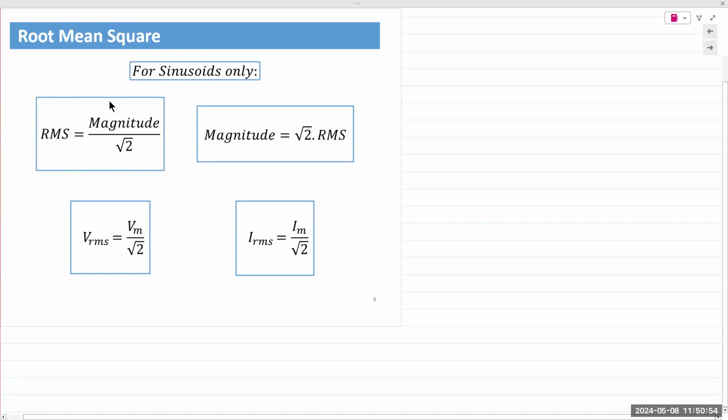So mathematically, V RMS is V M over √2, or V M is √2 times V RMS. Think back to the sketch I made. Mountains of dirt flattened out. The peak values of those mountains will always be higher than the average value. So magnitude values will always be higher than the RMS values, always. And you can see that in the mathematical expression, right? √2 is 1.41, almost 1.5 times the RMS values. So peak values will always be higher than RMS values.